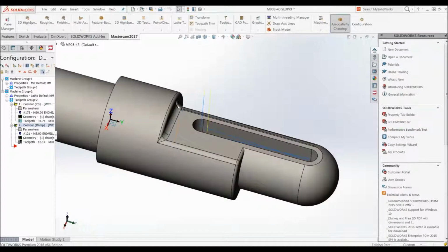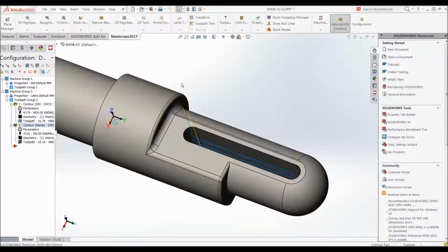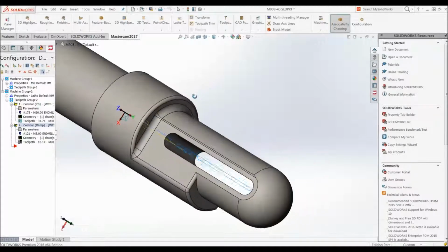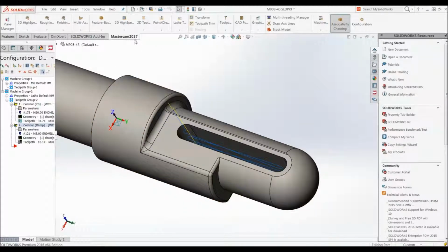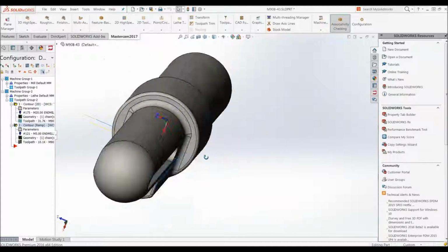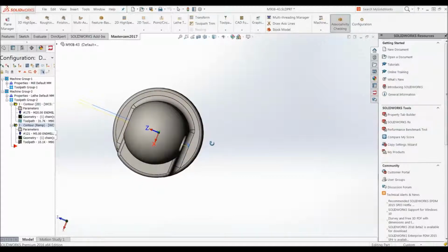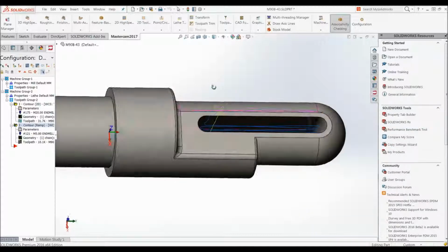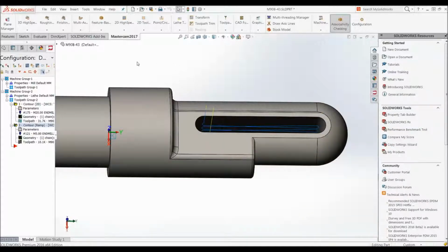And so you can basically machine every single one of your parts using that strategy. The only one that's a little bit different is the handle, where the toolpath you're going to want to run is an undercutting toolpath. So basically the same process. You're going to set up your lathe plane first, and then you're going to set up a mill plane relative to that so that your Z-axis faces just like we had here, so your cutter is coming from the end of the part. And then you're just going to select an undercutting toolpath that can take that slot cutter basically over the outside of the handle and back down in.